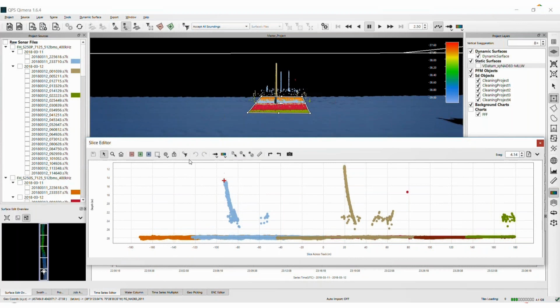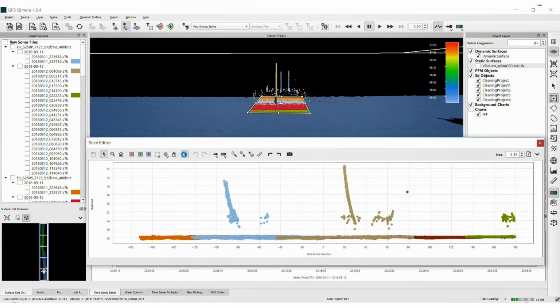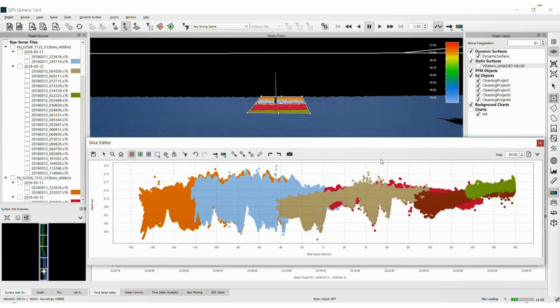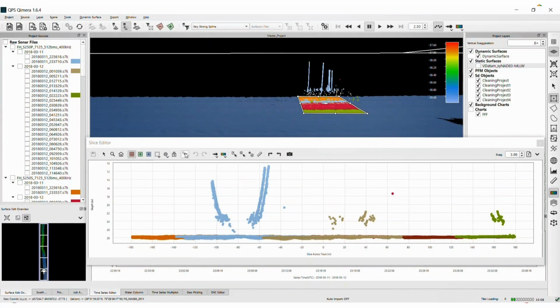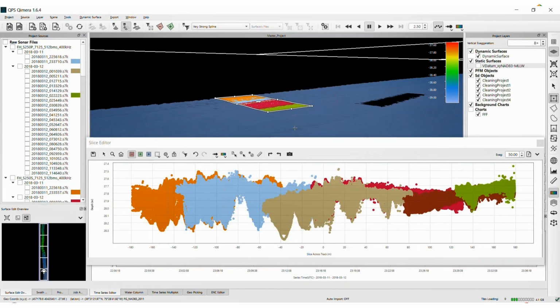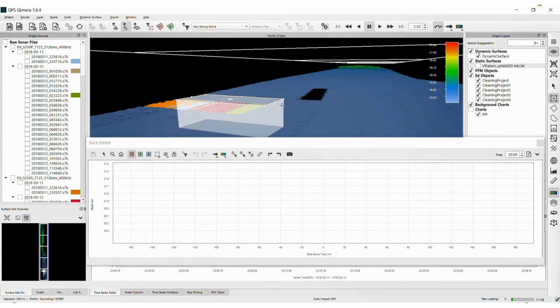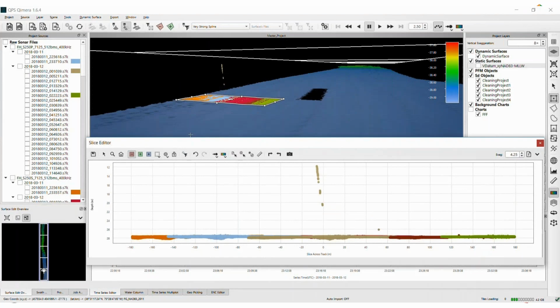It's very much customizable. You see there's these strong side lobes in here, and I'm going to put my spline filter back and run that. And just going to move along here and do a little more editing. And again, you may not even need to do this. You had to do it when you saw the spike, obviously, but you could also just validate the grid, and maybe you can live with the noise. But maybe you want a fully clean data set just to be totally safe, and so you're going through this. And again, the spline filter lets you do it quite quickly, and you have the nice 2D view with the customized 3D view there too.